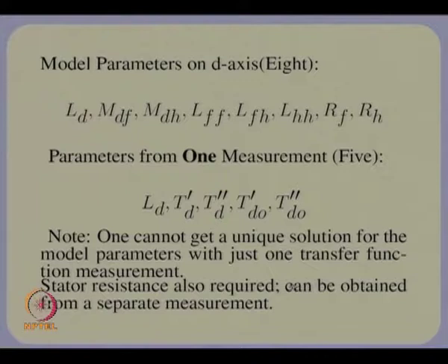Of course, we also require stator resistance. This is something I did not emphasize. It is usually a very small value, but it can be obtained separately. So, whenever I talk of standard parameters, implicitly I also mean the stator resistance, which can be obtained easily from measurement.